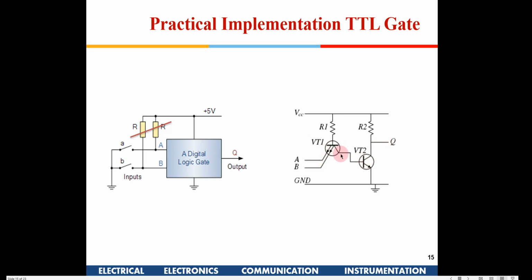This explanation in detail we will see later on. So for this transistor, this is a NOR gate, so whenever I give a 0 either at A or B, this transistor will get switched on and the output will go high. So that is how it works like a NOR gate.